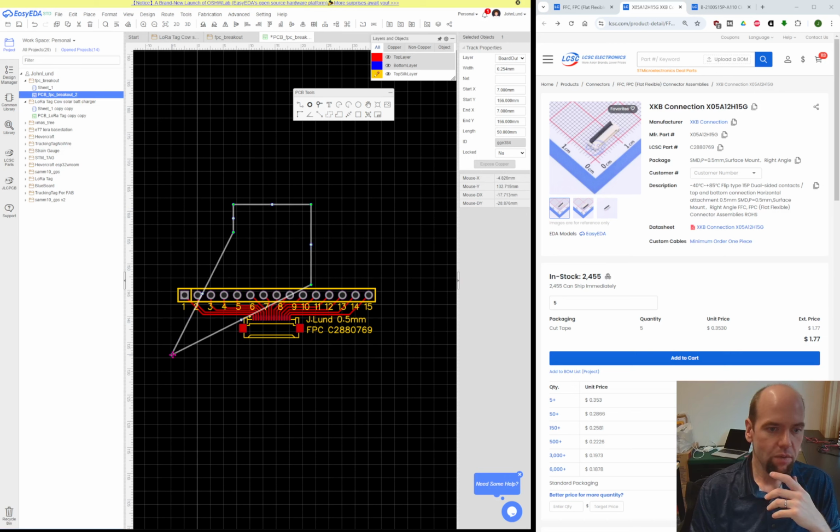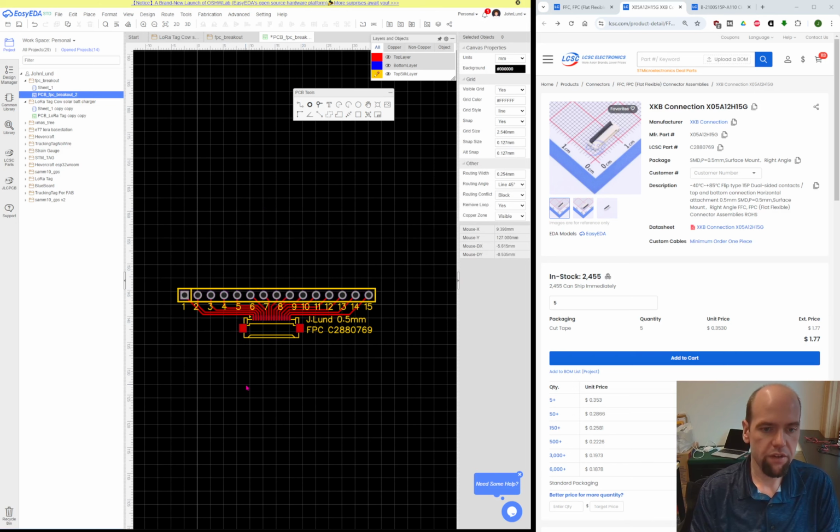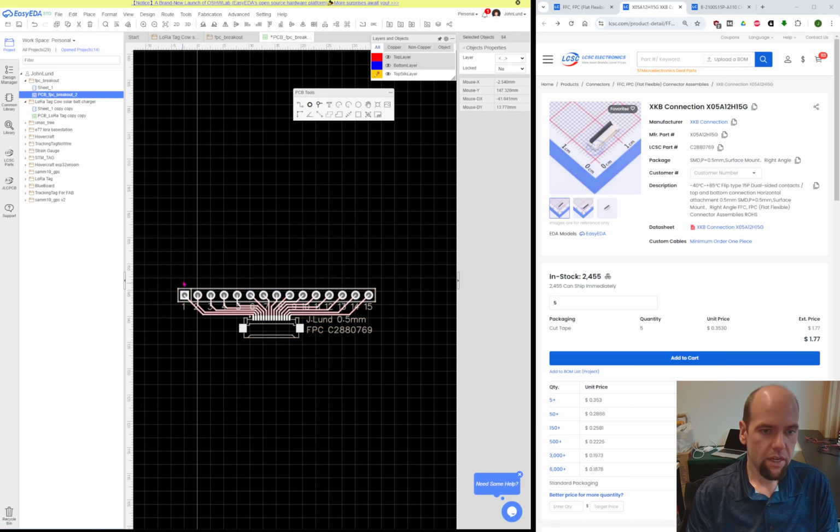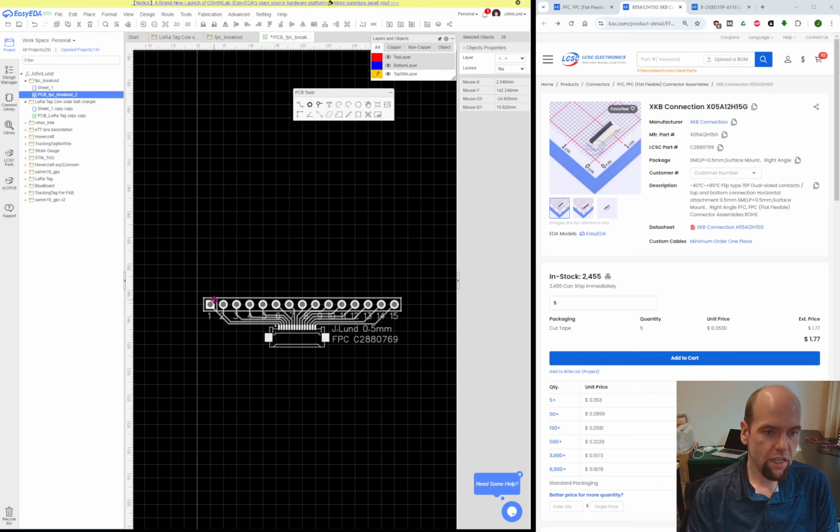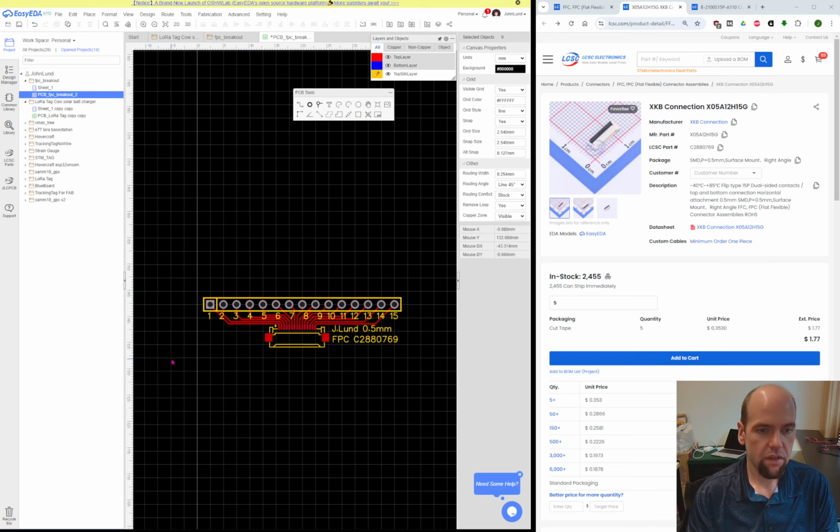So you can totally delete this if you want. If you click on the grid out here, you can change the snap size. This is pretty coarse, so I'm just going to change the snap size. The pin header is imperial units, so I'm just going to do 2.54 millimeters. And I might take this whole thing and grid align it a little bit. Yeah, that'll be fine. Okay, so now I'm going to go to board outline